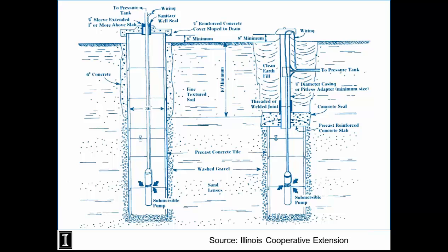They're not cemented. They're just placed on top of each other so water can seep in at each of those seams. And in these 2 examples, they put cement along this for the first 10 feet on one side, and they filled it with earth material, usually clay, the one on the right. And so then there's a concrete seal before you get into the actual well that'll provide a water supply. And so the bottom may be open with rocks in the bottom, or it may have been filled with a gravel, or it may just be native material.